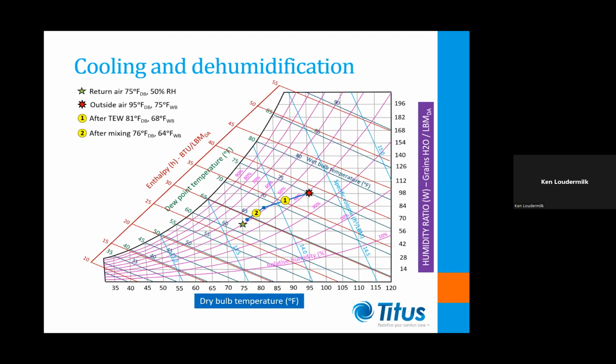Now let's plot the cooling and dehumidifying process on our psych chart. The initial sensible cooling process, labeled as line 3, involves cooling the mixture to its dew point temperature of 56.5 degrees Fahrenheit. Subsequent cooling to saturation at 51 degrees then lowers the mixture's moisture content from 68 grains to around 56 grains.